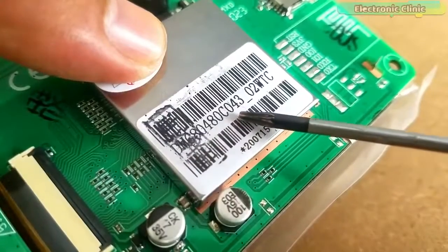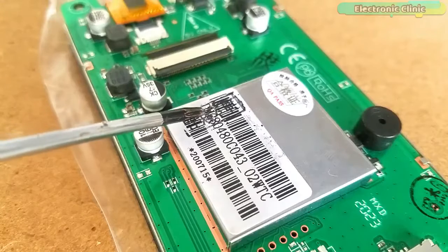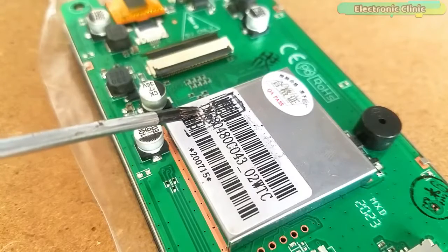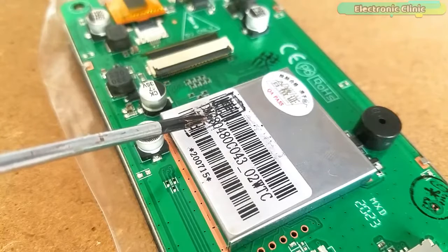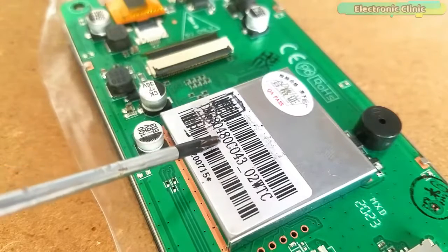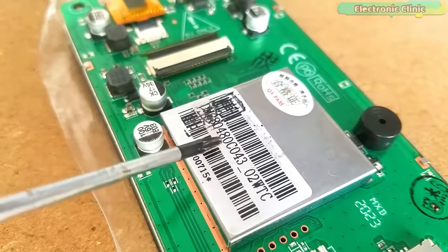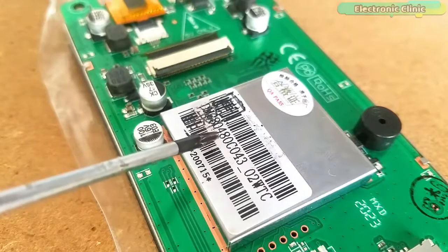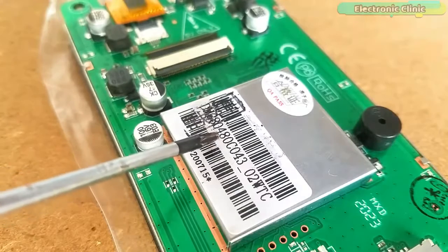The Dwin Smart LCMs follow a naming rule. The first 2 characters, DM, represent the product line code. The third character represents the color code. For this touchscreen, G means 16.7 million colors. The next 5 digits represent the touchscreen resolution. For this touchscreen, 80480 means this is 800 by 480.